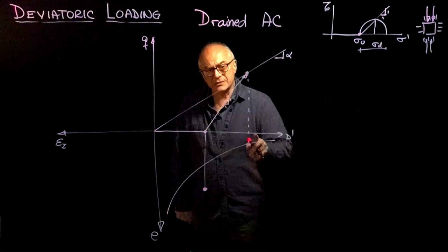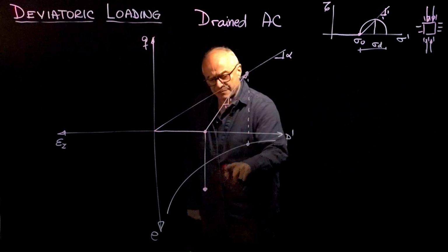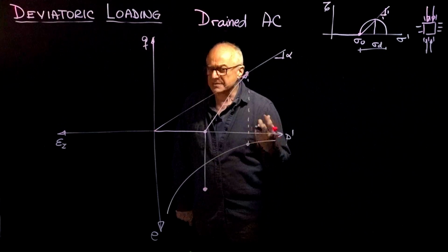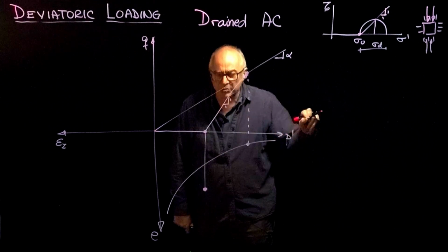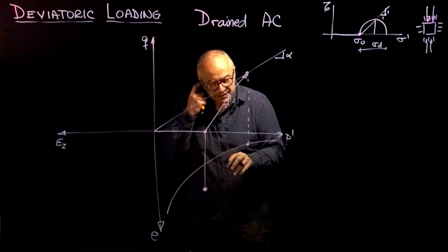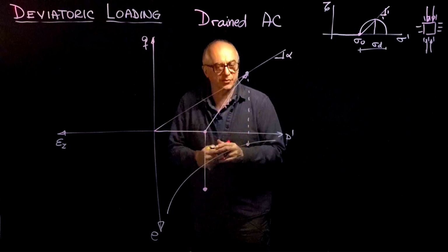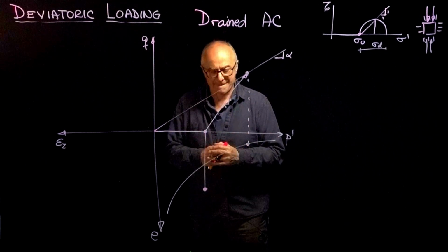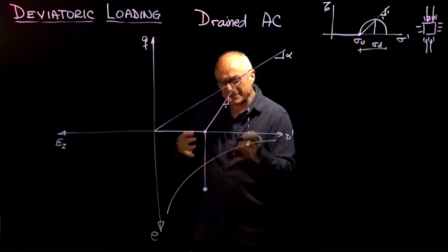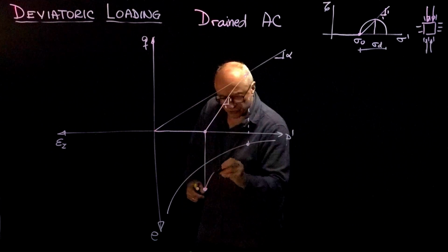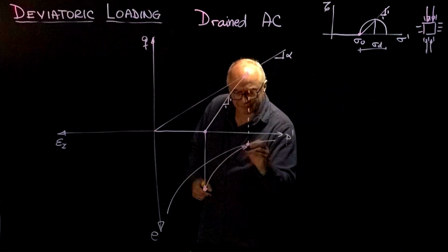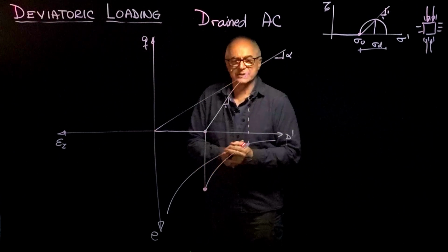Now, how did it go in this space? I don't know. That's the beauty of the triaxial test. We actually measure how much water comes out of the specimen in this contractive specimen, and I can determine the volumetric changes. But at the beginning, this is going to contract quite rapidly and then asymptotically go to the failure line. So I'm guessing that it's going in that direction.